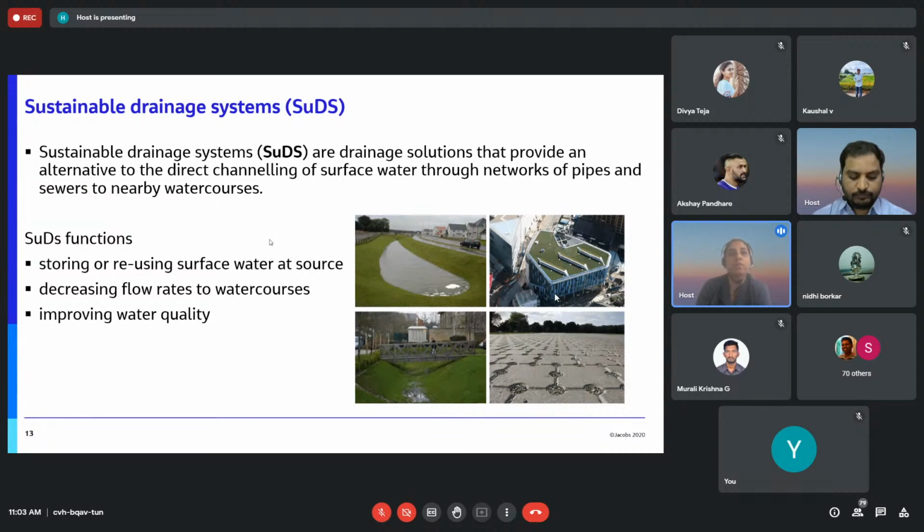So we must consider the flow rate of the water when the conditions were brownfield. Omkar talked about what brownfield and greenfield are, like without development and with development. Before any development, we don't have any concrete surface, so water can percolate into the ground, and therefore the flow into the water streams is less.